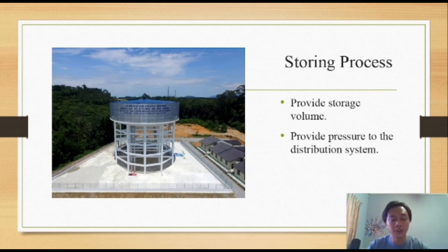So how does this storage tank work? A storage tank allows the use of constant flow in the distribution system. Pumps that fill the storage tank are operated by controls which start and stop them as the water level in the storage tank rises and falls during the day. When demand is high, the pumps cannot keep up with the requirements for water and the storage volume will be reduced. When demand is low, the pumps have excess capacity and are able to refill the storage tank to full for the next high demand period.